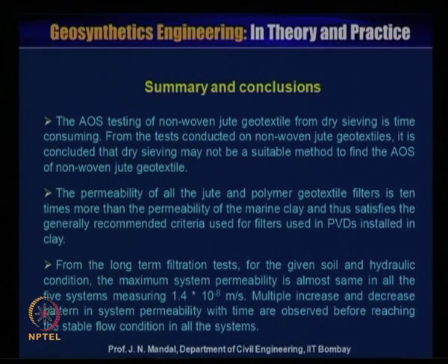Now, summary and conclusion. The apparent opening size testing of non-woven jute geotextile from dry sieving is time consuming. From the test conducted on non-woven jute geotextile, it is concluded that dry sieving may not be a suitable method to find the apparent opening size of non-woven jute geotextile. But in the majority of the cases we have performed the dry sieving.